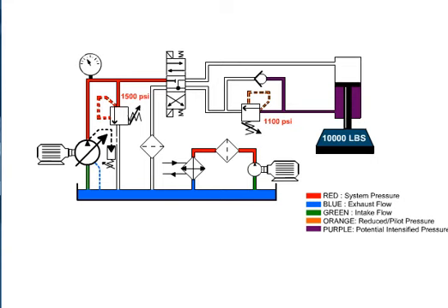The counterbalance valve has to be set slightly above the load-induced pressure. When shifted, the directional control valve applies pressure on the cylinder piston. This, in turn, increases the back pressure, causing the counterbalance valve to open, allowing the cylinder to lower the load at a controlled rate.